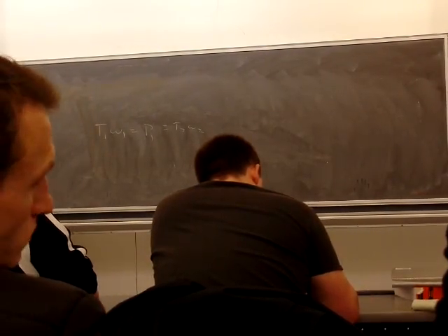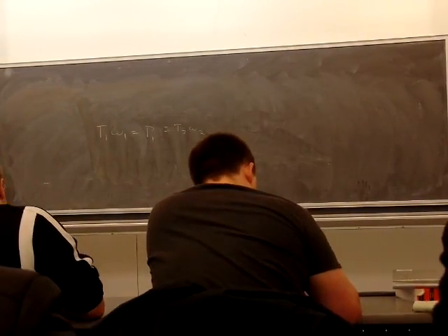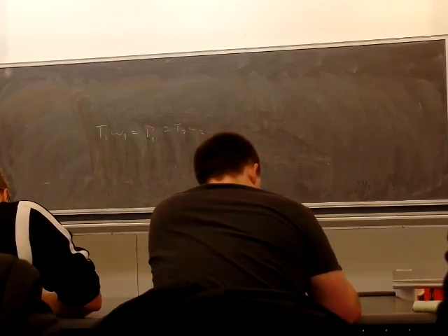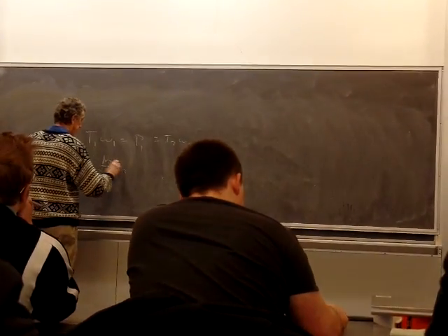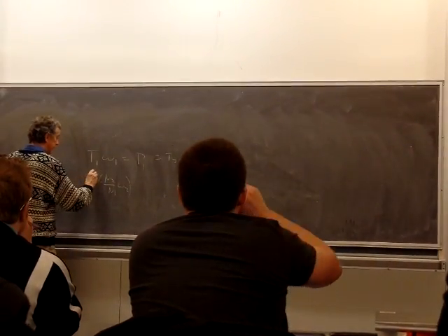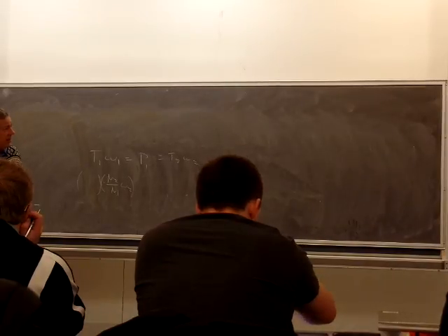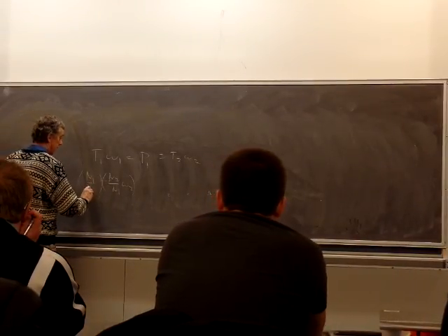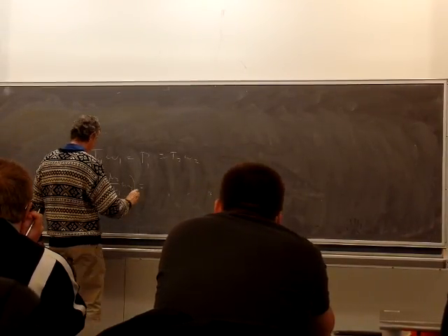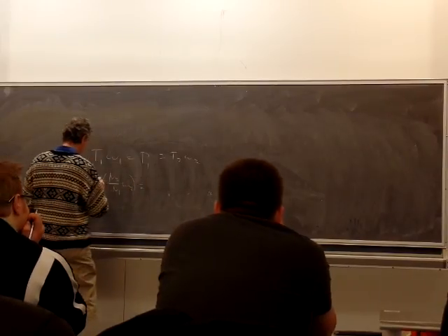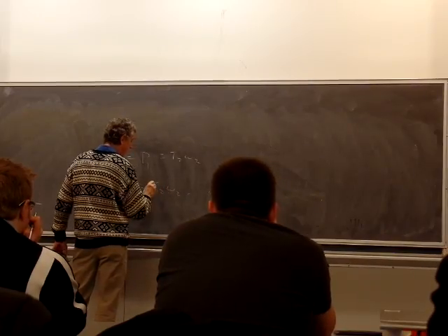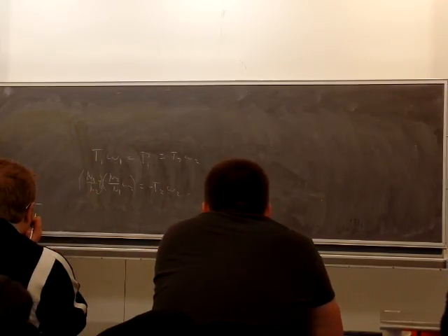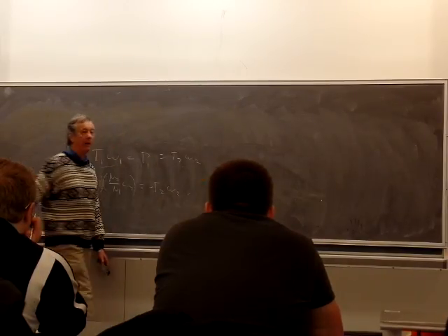That's the case. Now let's check. Well, you just replace omega 1. I have N2 over N1, minus that here, and T2 N1 over N2, which is equal to T2 omega 2. Minus sign means I'm just going the opposite direction. Okay? So, power in equals power out.